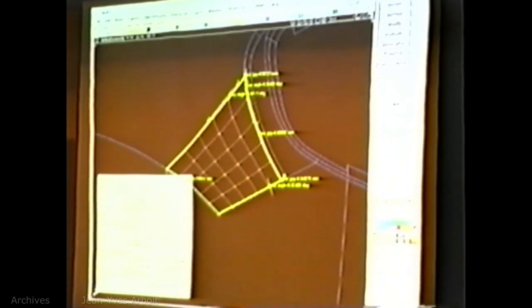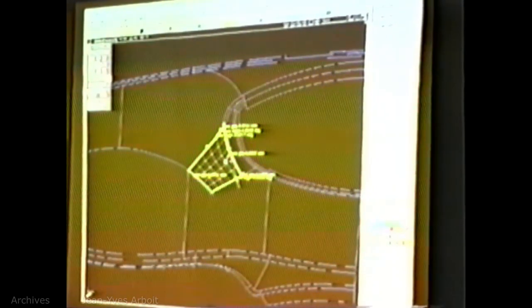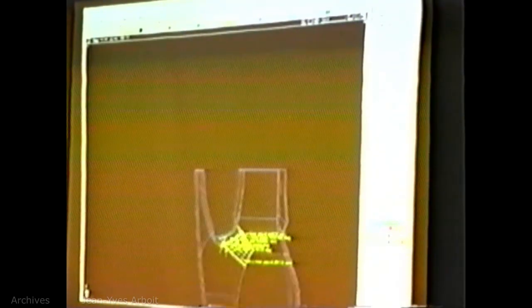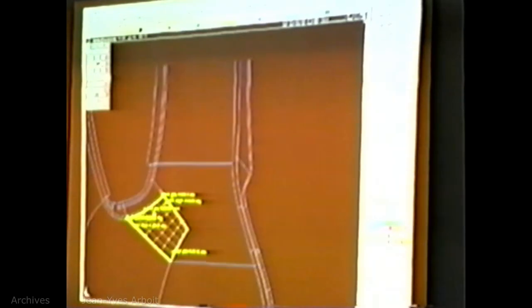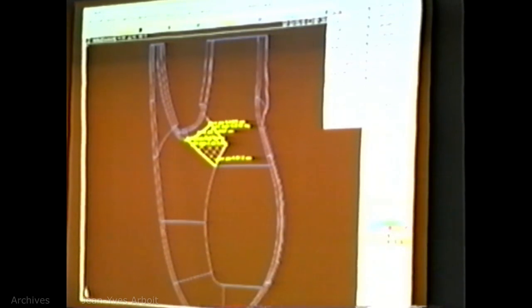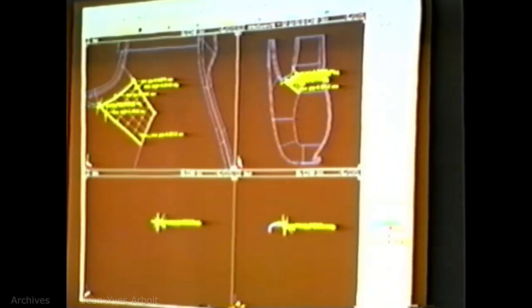Oh, okay. One more difference here. If I put this in a plan view, actually I need to go to a real plan view. One thing that's unfortunate, I think, right now is that although this is orthographically in a plan view, you can't create geometry. In other words, if I try and create a curve here, it still thinks it's a perspective view. Hopefully that can be changed, but I don't feel like it will for this version anyway.